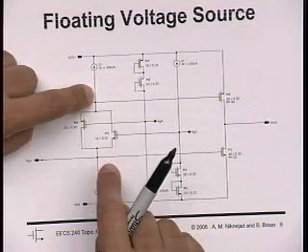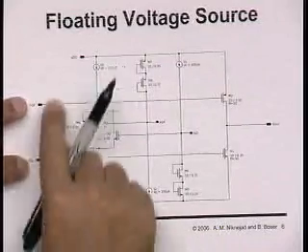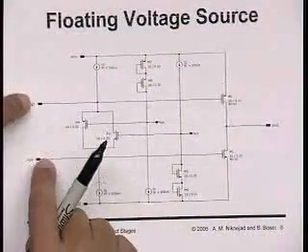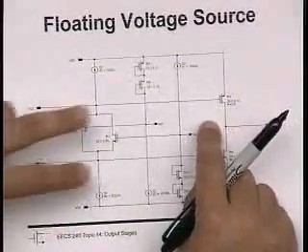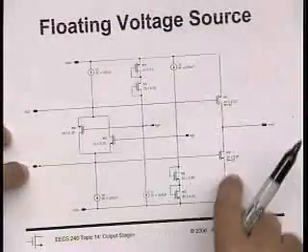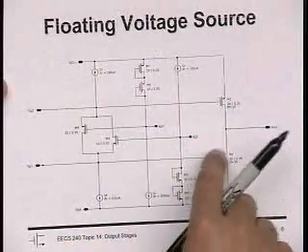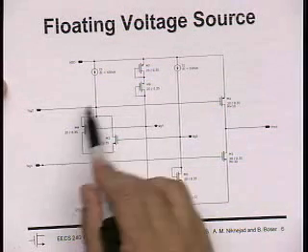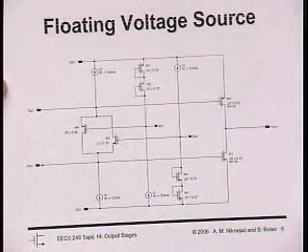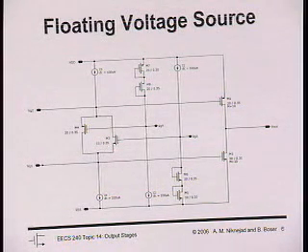And I've also produced, as long as I can drive this with the same polarity signal, I can dump a current into both of these nodes and raise this voltage or decrease the voltage, right? If I dump current, both voltages go high, this device turns on. If I pull current out, this whole thing drops. This device turns off, this device turns on, and supplies the load current. So this implements our floating voltage supply. Okay? Questions or comments about this?